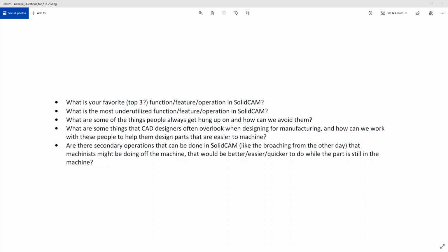And one that I don't see very often is called a cogstail drill, and it's set up for deburring holes. So it's a spring-loaded carbide little bit where it will come down in the hole, sit there with a dwell for a second to deburr, and then it will push straight through. And by spring-loaded, it will pop back out once it hits the bottom of the hole and deburr the top side and the bottom side of that hole within a matter of seconds. If you have to pull that part out and do secondary work on it and the operator still doesn't have enough time in the machine just to barely unload and load parts, that's good to do it that way too.